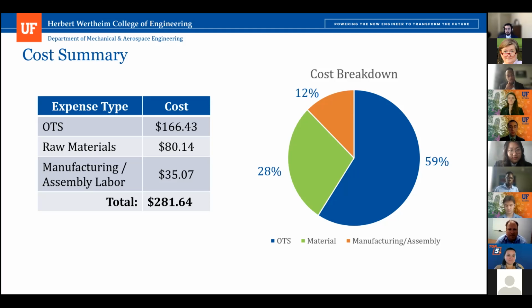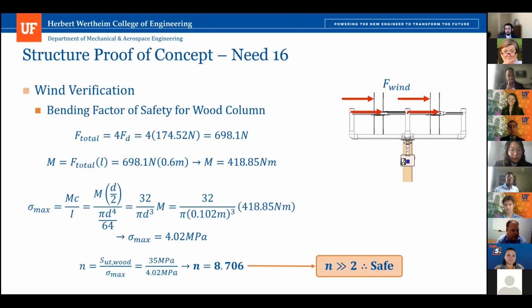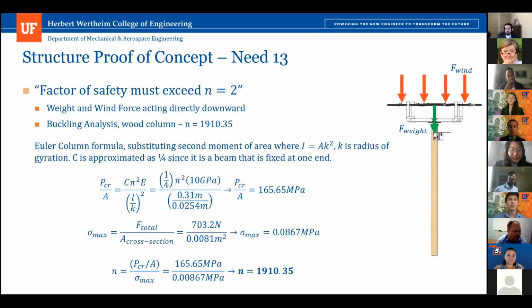And then when you did your buckling analysis, you talked about a factor of safety close to 2,000 or whatever. Anytime you get a factor of safety greater than 4, just say that you have ample margin. You scare the customer sometimes when you give huge margins of safety, because basically you imply that you're wasting their money because you've got too much material. So just be careful how you address those sort of things.